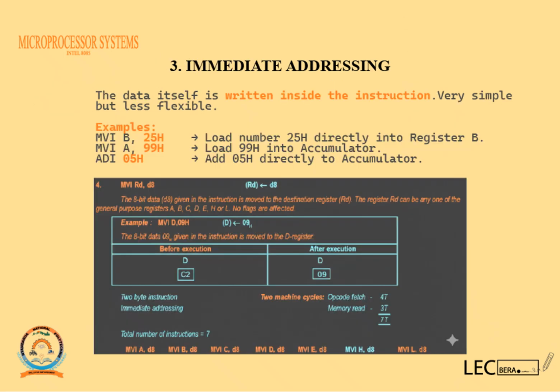So far, in the first example, when the operand is inside the register, we do what is called direct addressing. The second scenario is whereby the data inside the register is not actually the data itself, but an address to a memory location. And we say that one is an indirect addressing. In the first two examples, the data is inside either the memory or inside the register.